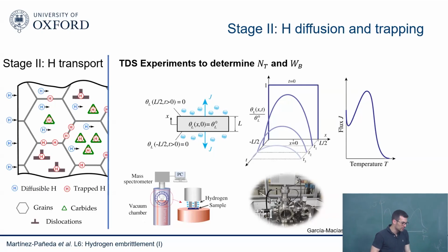For example, you can change the dislocation densities. You can do a heat treatment, annealing, and see whether those peaks move away. How do they change? You can put in more carbides. There are always things that you can do from a metallurgical point of view, and by experience, we tend to know more or less now which traps are stronger than others. But it's a complicated problem.